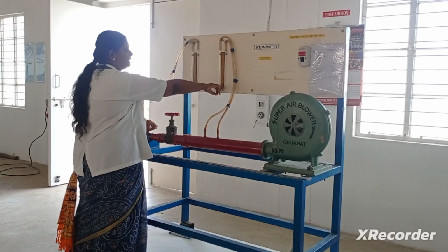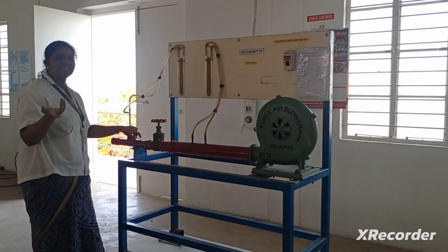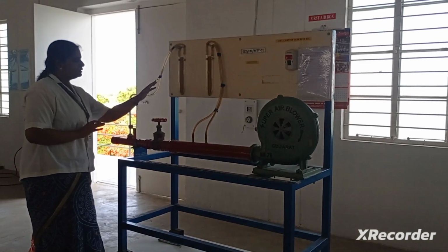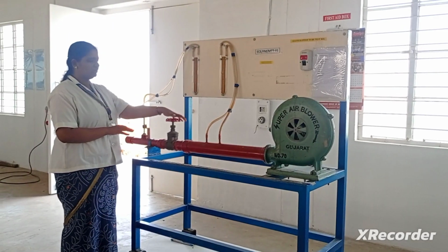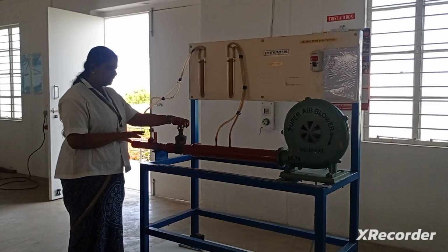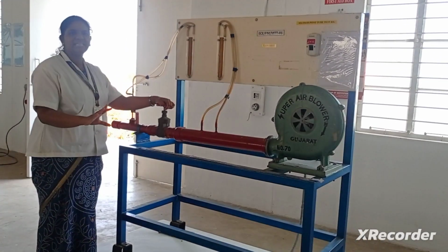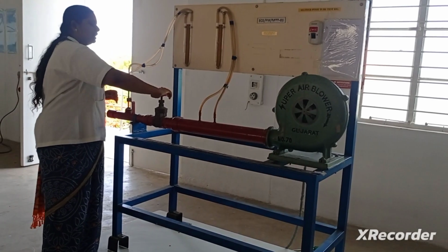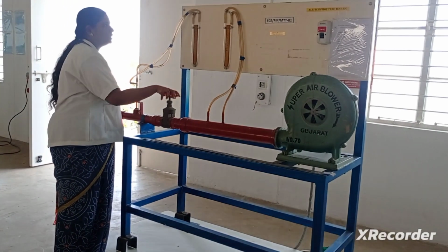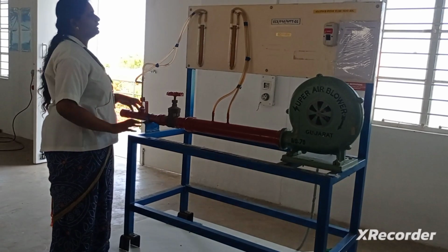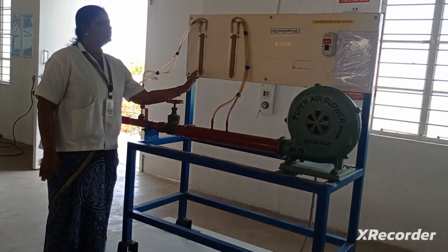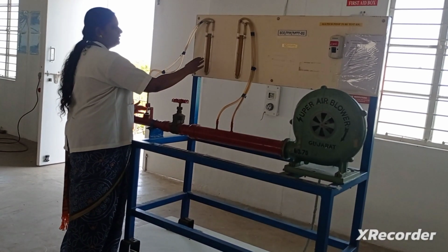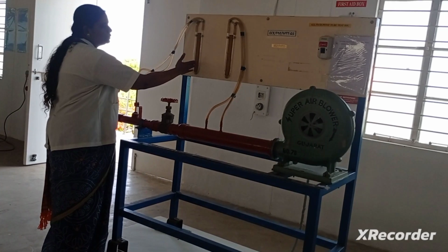Without resistance, we can take the head difference value, which is also considered as the pressure value from the air blower. With resistance, we have a valve here. By opening and closing the valve, the resistance gets changed. First, we take the value in the closed position. From the closed position, you have to note down the readings from this and this U-tube manometer. Once you start the blower, it will definitely change on the two sides of the manometer.